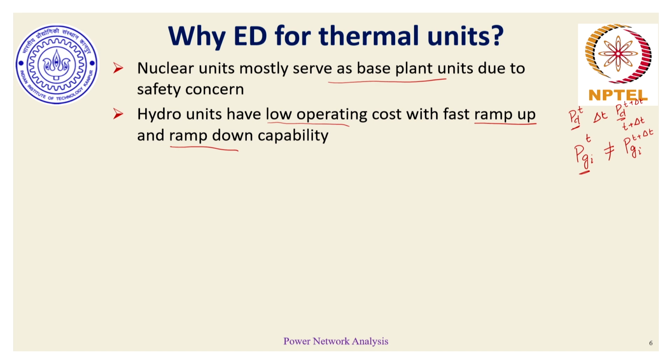Often our power plants, specifically thermal power plants, since they have a lot of rotating devices involved, in the sense there is a boiler involved which has its own mechanical inertia. Temperatures in a boiler cannot change instantaneously. Boiler takes time to heat up and also to cool down. So, if the boiler is taking time to heat up and cool down, the corresponding steam exchange would also take time, and as a consequence, the turbine action will also take time.